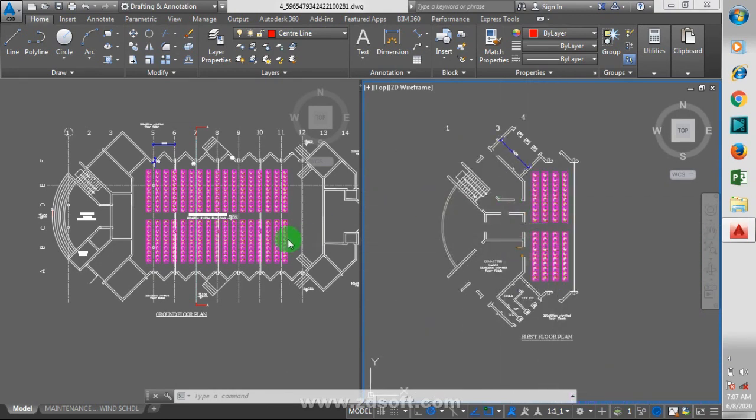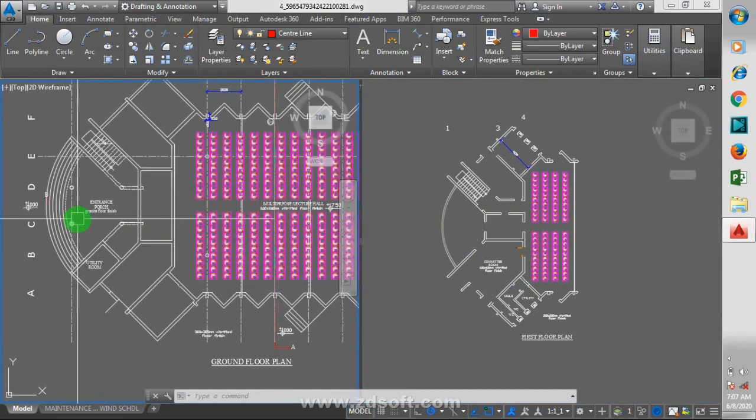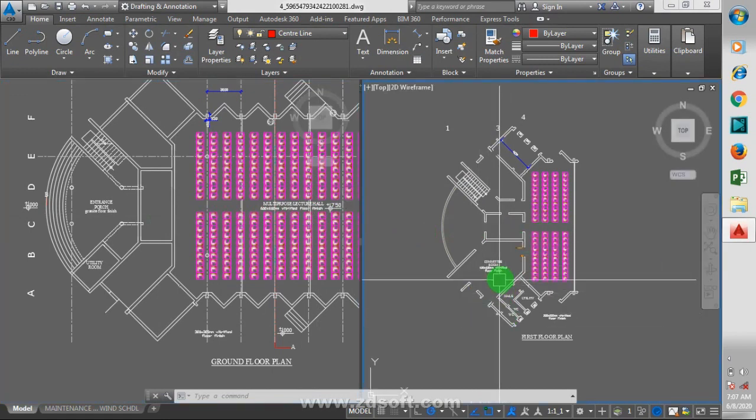Another thing you must put into consideration is the relationship between your first floor, the floor that is coming on the ground floor. Okay, there should be a very good relationship, so as for you not to have much point load acting on your slab. So you must actually think very well on how your beam lines will follow, where it will follow, and the positioning of your columns. So try as much as possible to reduce your point loads.